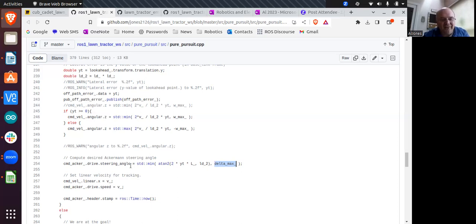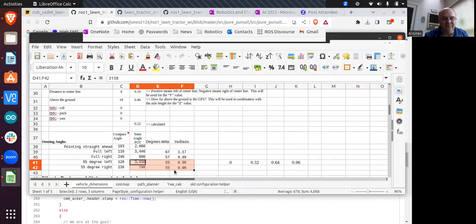So anyway, now I've been passing. I have a program that reads command velocity angular Z and, you know, gets it over to this steering control motor, but I need to change that to use this steering angle instead of the rotational velocity, because I'm in actual fact set up to deal with steering angle, not rotational velocity, which these are my furthest left and right extremes.